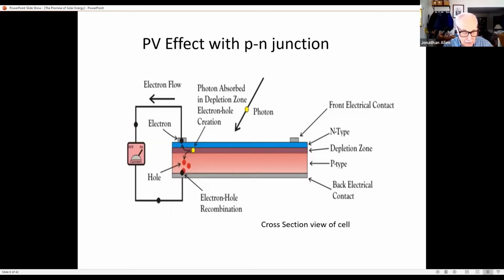When the silicon forms its crystal, each phosphorus atom fits into the lattice and replaces a silicon atom. But the extra electron, that fifth electron, is left out of the bonding structure, so it's free to move about. Now, the lower level is doped p-type, p standing for positive, with valence 3 elements, such as boron. It leaves an electron vacancy in the bond structure, which we call a hole.